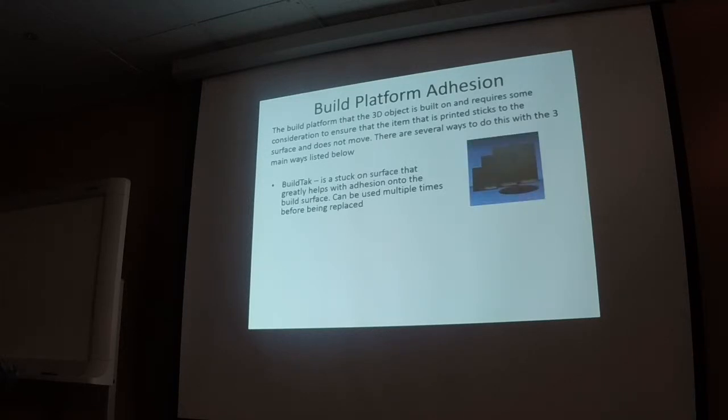So build tack is a sheet that I stick to my build plate, and I found it really good. It makes it really simple. It sticks very well and lasts quite a bit of time. I was able to produce, I reckon, 300 clips with one sheet, over a period of three and a half weeks of constant use. So it lasted quite a bit of time.